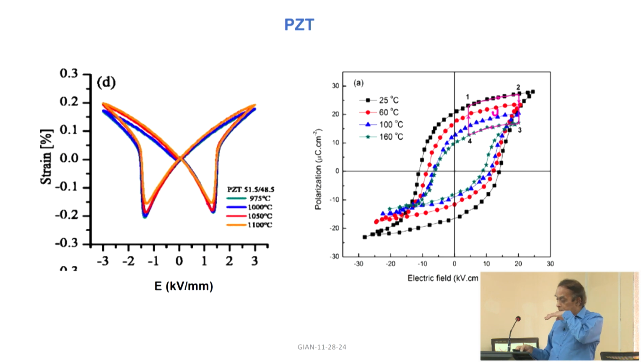So, when you make PZT, you have to be extremely careful, because lead has a tendency to evaporate and escape from PZT. So, in order to avoid any loss of lead that you need in the PZT, you always disperse some lead around it. So, that will compensate for any loss, and then you can get stoichiometric PZT if you make it.